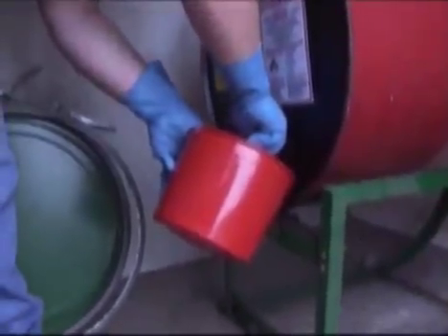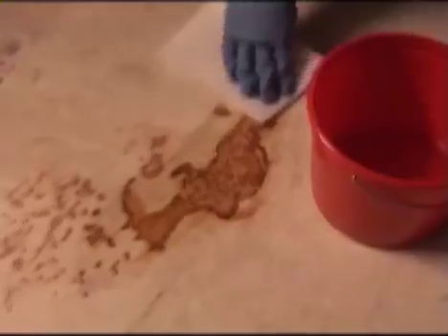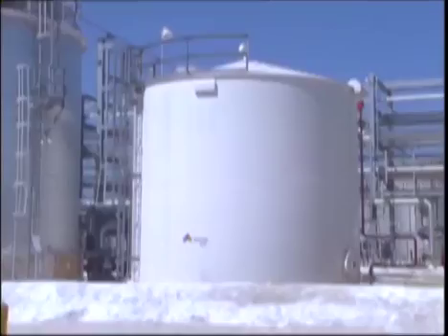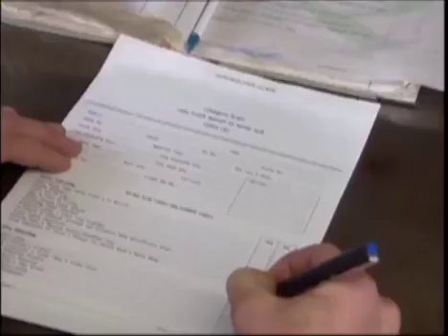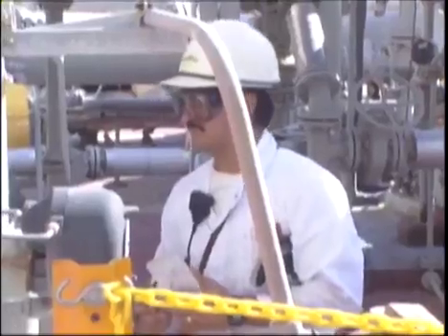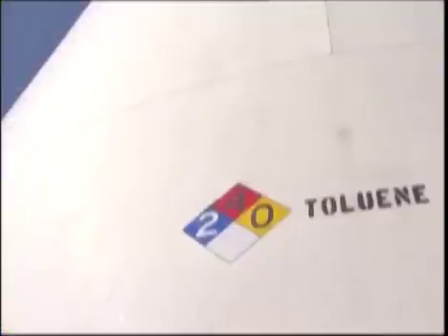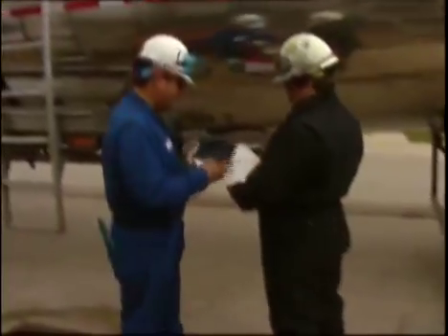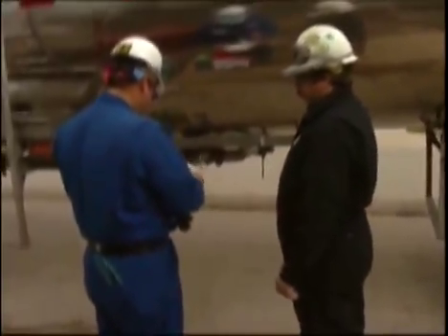Portable containers, used to transfer hazardous chemicals from labeled containers and intended only for the immediate use of the employee who performs the transfer, do not require labels. For stationary process containers, such as storage tanks, the employer may use signs, placards, process sheets, batch tickets, operating procedures, or other written materials in lieu of affixing labels. This alternative method must identify the containers to which it is applicable and convey the information required on secondary containers. The written materials must be readily accessible to employees in their work area throughout each work shift.